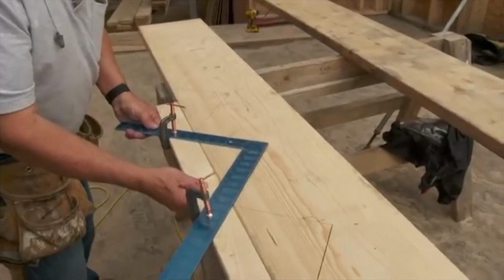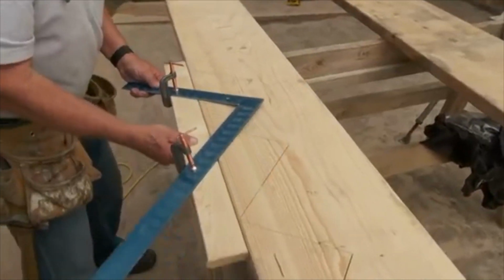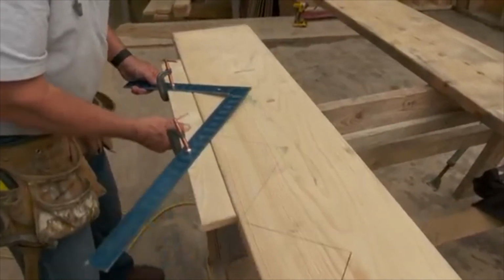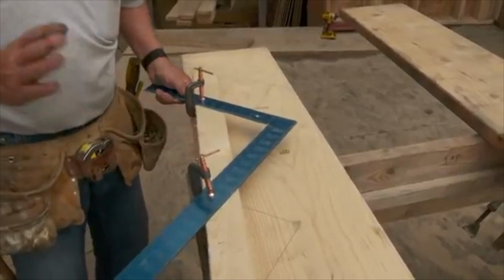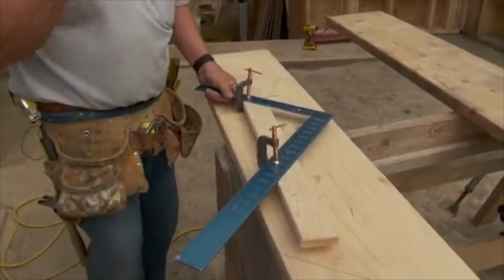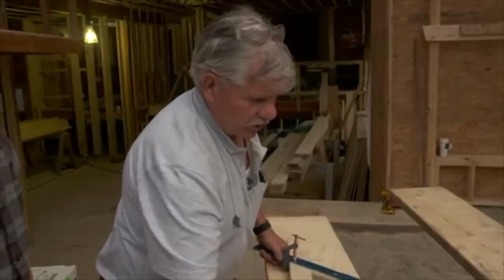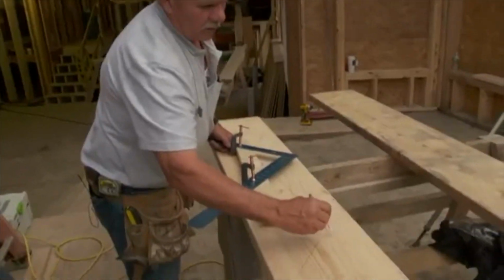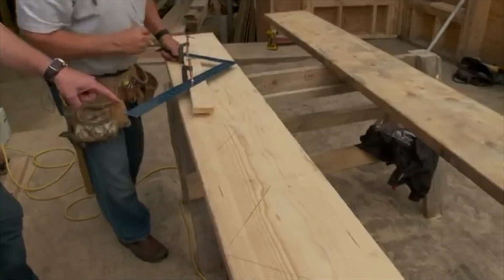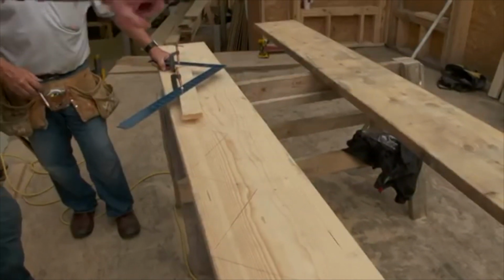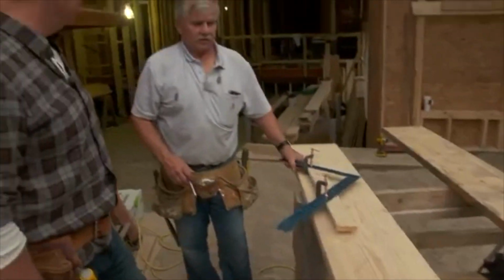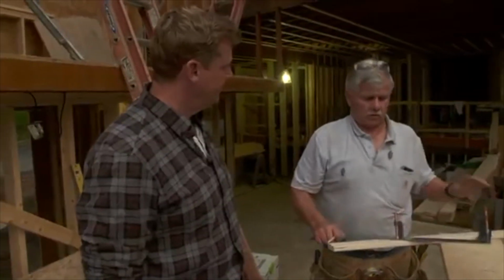So now I have a straight run, I go up here like that, and I mark them all off. Once I've cut my first one, I then use it as a template. So instead of going back to the framing square for stringers 2, 3, and 4, you go back to the template, lay it out, and use that. Because if I laid each stringer out with my framing square, I could be off a 16th or an 1/8 inch on every one of them. Start right, use a template.